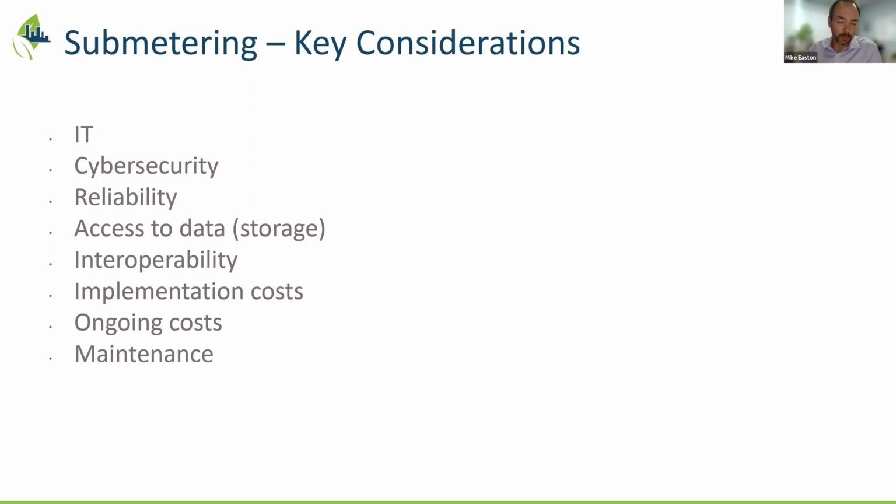Yeah, sure. You'd mentioned earlier that electrical meters were kind of the mainstay of building level or sub-meter solutions, and that is very accurate. Because of that, electrical meters tend to have a very long field life. They typically don't need recalibration for around 10 years, but if you want to be on the ball, you could do it every 5 years.